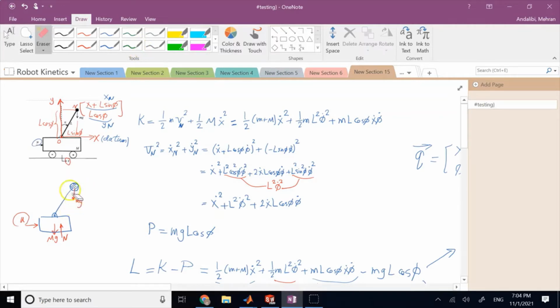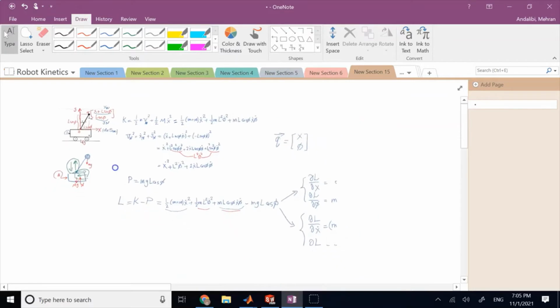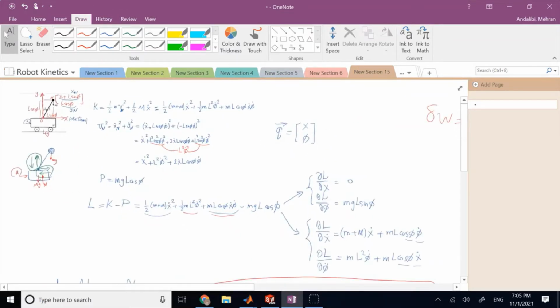And if I want to focus on each individual component here, you definitely know at this pin I have x and y reaction applied from the block to the mass, and then there is reaction to those which are applied from the pendulum back to the block. But since the net work done by these forces at that point is equal to 0, they will never show themselves anywhere, and so that's the beauty of this method is you can skip what?